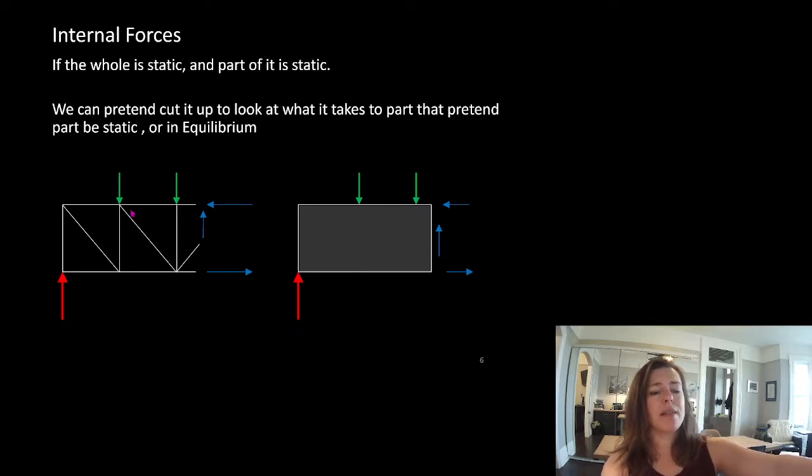So what if we just imagined all of that truss was just a blob? We know that we can solve for all of these internal members that make up the web of this truss. But when we did this cut right here, what was happening internally over here was irrelevant. If we made the cut here, different story. But when we make the cut right here, we could have just drawn this as one big blob. Okay, so it's the same thing right here. I've just redrawn this and grayed out what's happening over here because I don't care about what's happening in the other spots. At this moment, with a different cut, I would care, but not for this cut.